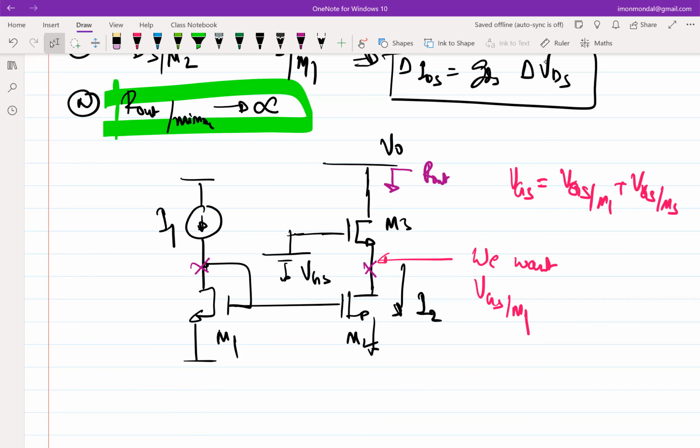Maybe at a particular temperature, you will get very good mirroring. But if you change the temperature, your mirroring will not be good. It might also so happen that, for those of you who have been taking device courses, you'll also know that when you make a wafer, it's not necessary that every batch of wafers will have the same threshold voltage, right? They can have a variation. Okay, so circuit designers model those as corners. So typically, let's say it has a threshold voltage of 500 millivolt. Then there will be a bell curve around that 500 millivolt, right? So everything has a distribution. Maybe the threshold voltage distribution can go from 400 to 600, right?